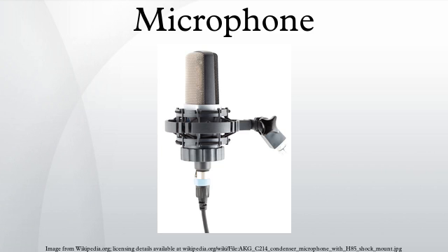Fiber-optic microphone. A fiber-optic microphone converts acoustic waves into electrical signals by sensing changes in light intensity, instead of sensing changes in capacitance or magnetic fields as with conventional microphones. During operation, light from a laser source travels through an optical fiber to illuminate the surface of a reflective diaphragm. Sound vibrations of the diaphragm modulate the intensity of light reflecting off the diaphragm in a specific direction. The modulated light is then transmitted over a second optical fiber to a photodetector, which transforms the intensity-modulated light into analog or digital audio for transmission or recording.